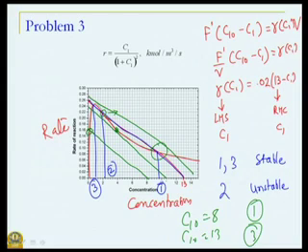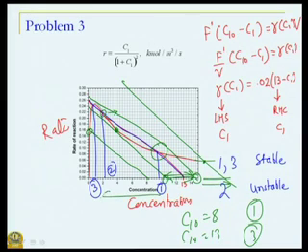So, in this feed concentrations, you can work out what those exact numbers are. In this regime, we will have 3 steady states. Any feed concentration on this side, you will have only one steady state intersection. So, anything here or here, single steady state, but all those concentrations in between, we have 3 steady states.